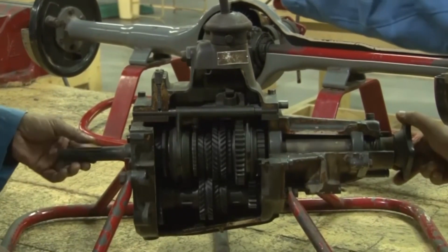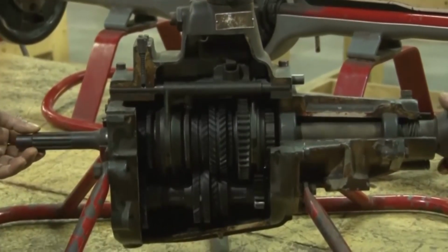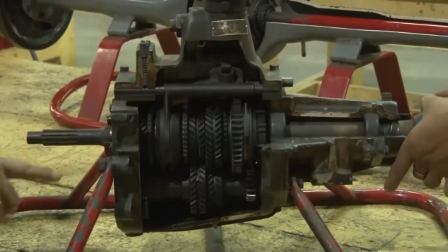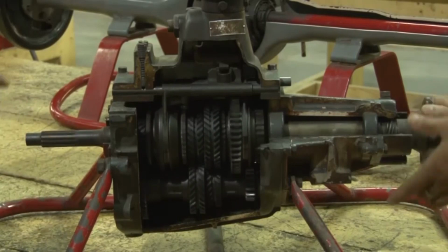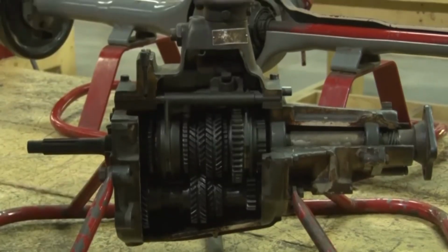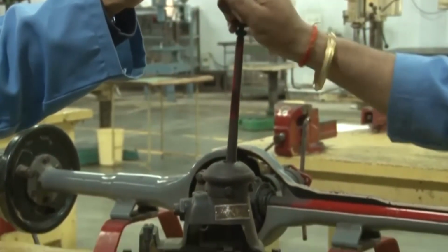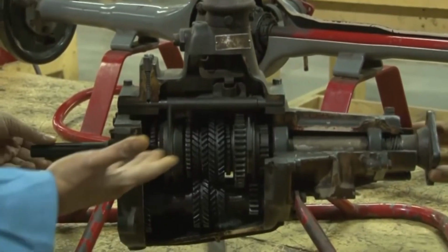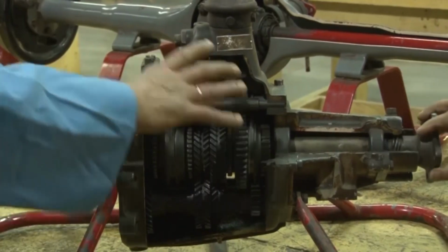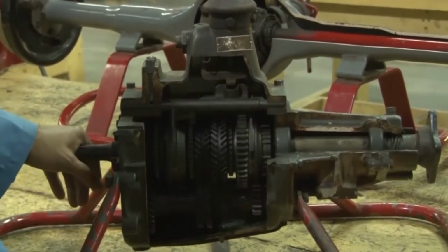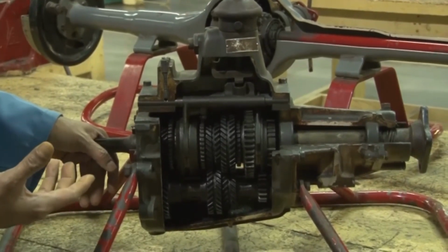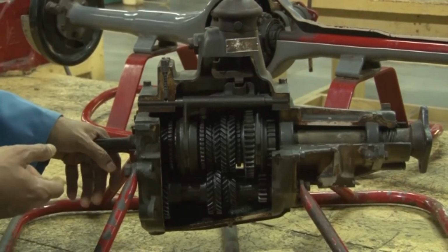And here you see this is the back gear, and in the back gear this input shaft is rotated in this way, and you see this output shaft is rotating in this way. So, this is the back gear. This way the gear is changed with the help of this, and then you can put it back to the neutral position, and neutral position means with the rotation of that you can see that this is not rotating. So, this is how in a compact way the gear drive or the transmission ratio is made in the gearbox of an automobile.